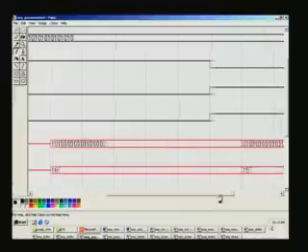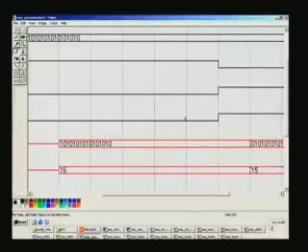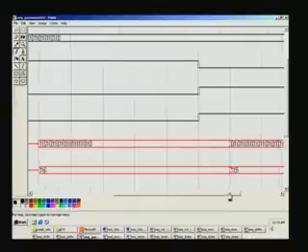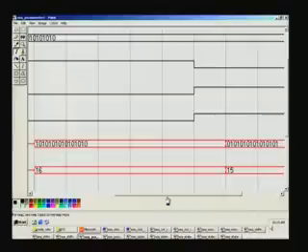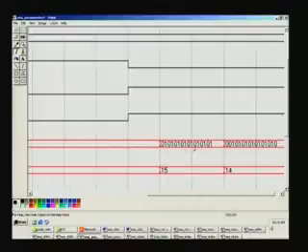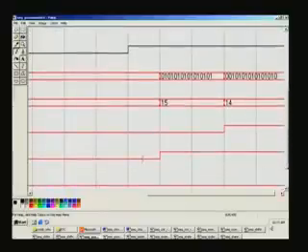What is this here, this R stands for a left shift here. So, initially left shift, but it is now right shifted here. So, it is made 1 here. So, hereafter this will be right shifted, including for the very first bit, that is why it is going right here, not here. So, now 1 0 1 0 we started with, now you can see that it is shifting, 0 1 0 1 here, and also it is a right shift.